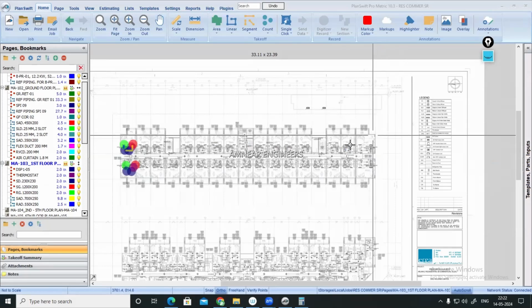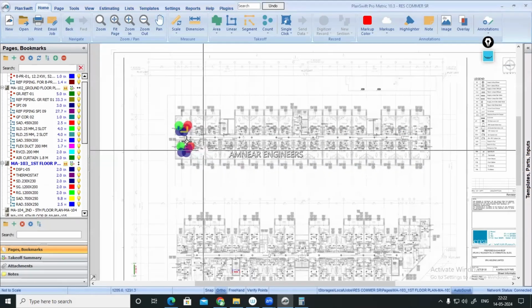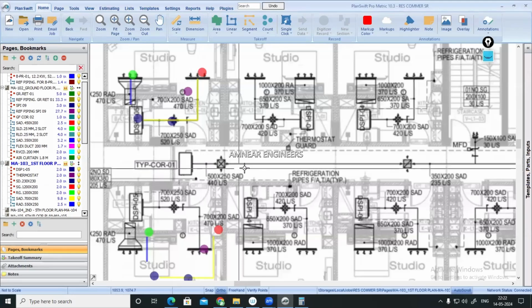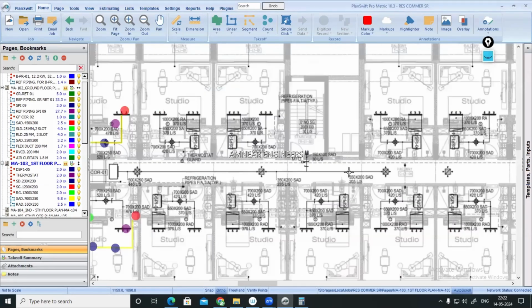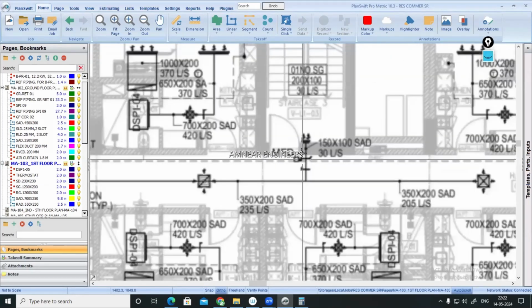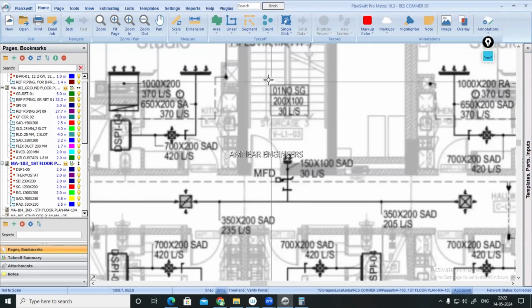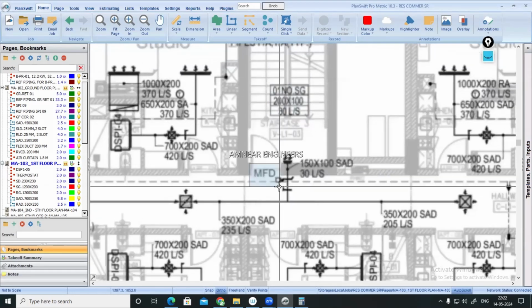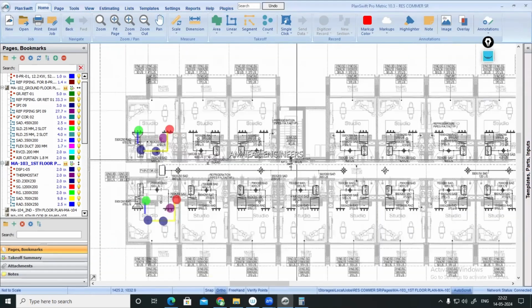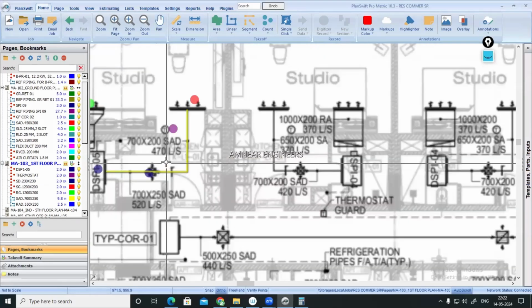The same way in the corridor, we have the other typical corridor duct. You can take the straight one, I am not repeating it. What grill do you have there? Supply grill. We are having an MFD there. Instead, all these are VCD only, volume control dampers. The function of a volume control damper is to adjust the airflow rate. We have studied this in the drafting classes.